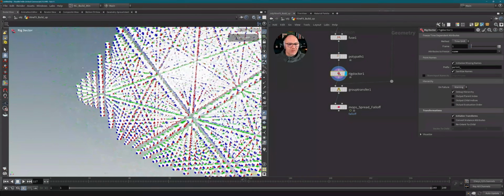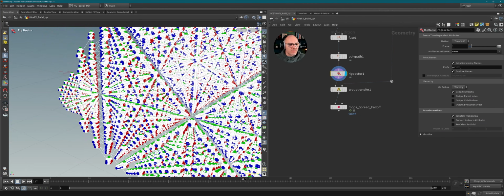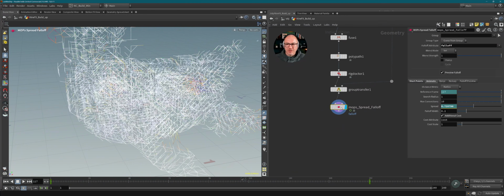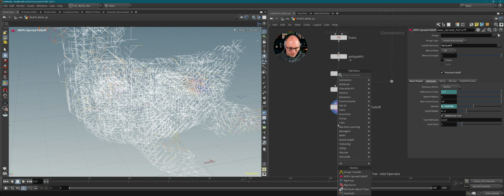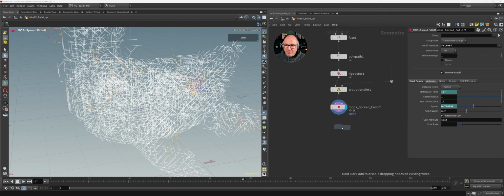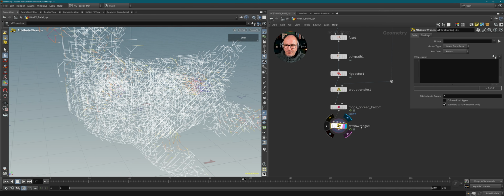If you take a look at these small white dots with the points pointing in these directions, we can now specify at which axes our blocks should rotate when they are building up. I want these to rotate around the x-axis, and I just want to specify this axis right away. So let's create a point wrangle here, an attribute wrangle that runs over the points. It's exactly the same actually. I will just call this set axis so that we know what we are doing here.